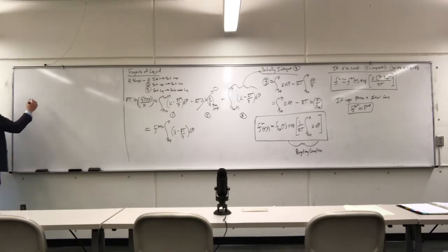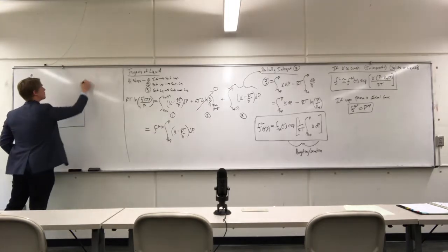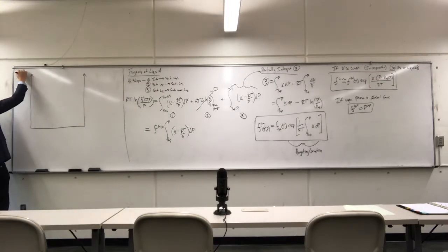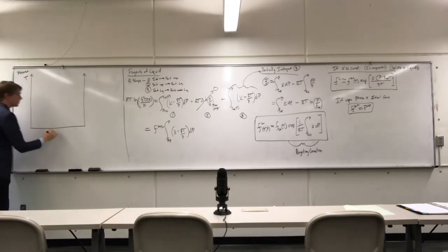Okay. The TXY diagram is intended to be a compact way to demonstrate phase equilibrium results. Basically, in the TXY diagram, the pressure is held equal to a constant, and we are varying the temperature of the system and the fluid composition.